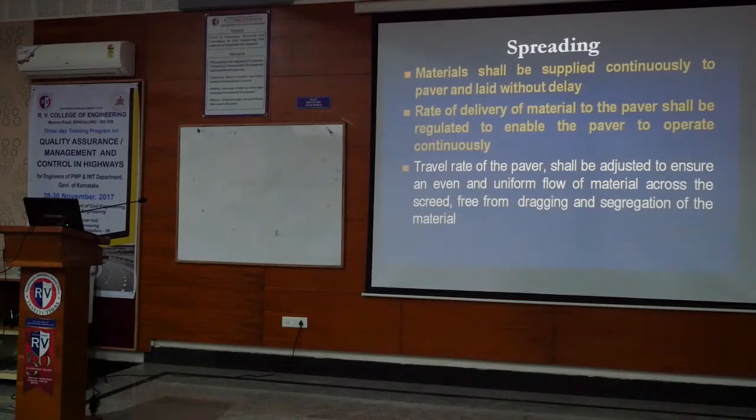We are creating weak planes. No wonder. The moment I stop my paver, that means I am creating a weak area there. So here and there I am stopping and creating weak planes. That means for the same stretch, the same length, the life and performance of the mix we do not get uniformly. It fails wherever my paver stops for some time for loading or waiting for loading to happen. That area fails first. We get raveling, etc. So this is more important.